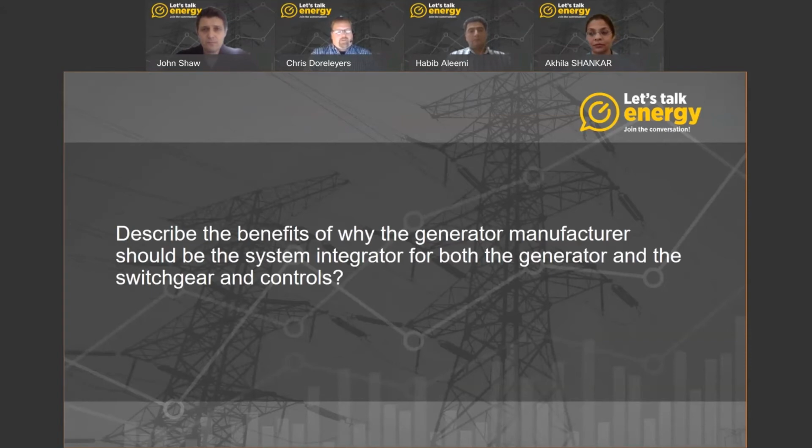we do have requests where we try to get the existing power generation assets ready for global adjustment mitigation programs. And specifically, some of the upgrades that come up are we can add SCRs to address emission requirements from the Ministry of Environment. Additionally, we can add hardware and software to address connection impact assessment and agreement requirements from the local utility, such as adding monitoring and control to meet the requirements of the local utility company for transfer trip schemes.